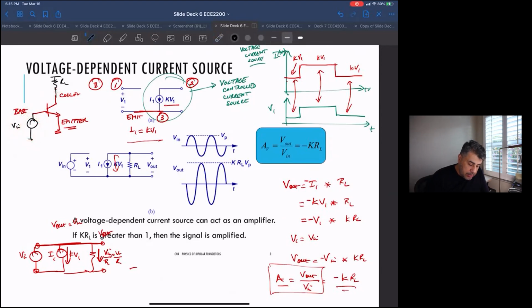Now, it is permissible, and sometimes you do it, to have a situation where the base is connected to the collector, which is the situation you were wondering about, this connected to this. That's used in a different circuit, like a current mirror, but I don't want to confuse the discussion.